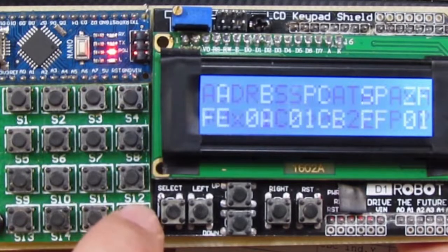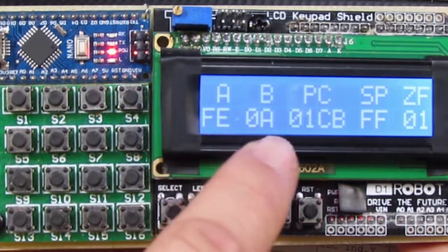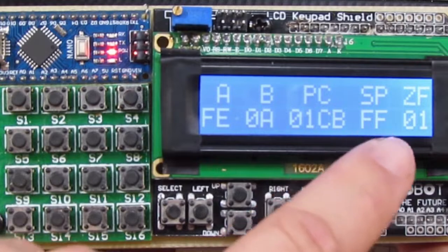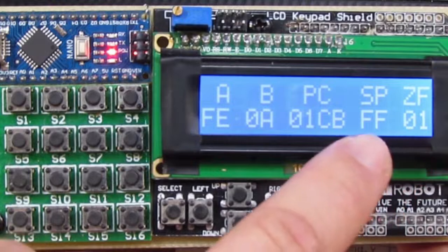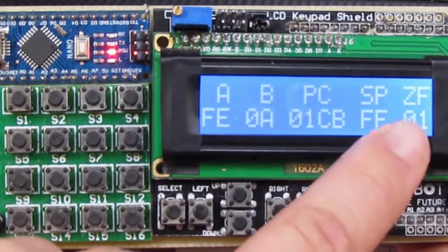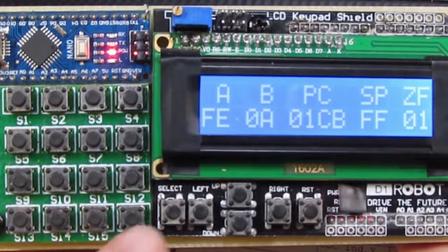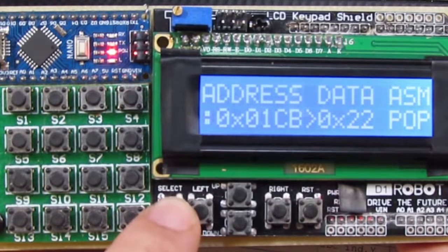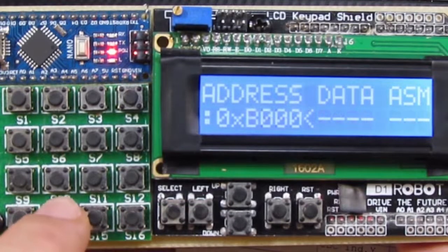Well, by the way, I can have a look at the debugger. So now we have the current values. After we've dropped the execution, we have the values at the A, B registers, and the program counter. The stack has dropped back, although we've been calling some functions. The zero flag is currently equal to 1. Probably it doesn't make sense putting 0 here, but anyways, just for the sake of layout. So let's drop back to digit mode, and let's go with address 0000.